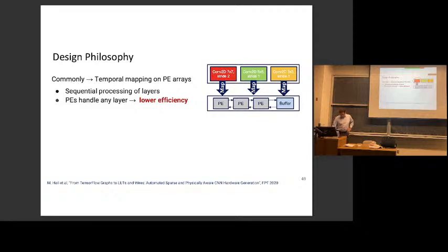After you're done with that convolution, you've got some temporary data stored in this buffer, and you need to go on to the next layer of the neural network, and it's different. Maybe this is another two-dimensional convolution, but it's got a 5x5 filter size, so this filter's smaller. The stride is 1, so it's now producing one output value for every one of the input locations in your image or feature map. And you map that to these PEs. So you set the muxes and control logic differently, and they go through that layer.